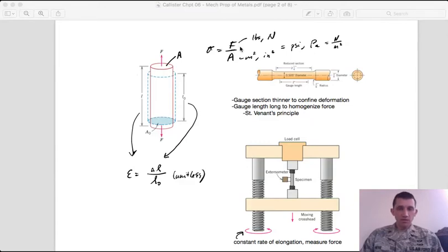When we're looking at a material property, we don't want to think in terms of a load, because we would have a different result if we made a different choice for the size and shape of the sample. And so here we want to be careful to divide out the cross-sectional area, so that it doesn't really matter what the size of our sample is, we can achieve the same stress within that material that we're measuring the mechanical properties of, right?